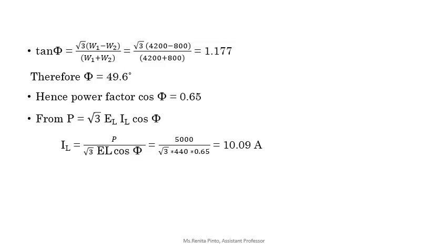Next is the power factor. How can you find out the power factor? You already know there is an equation: tan phi equals root 3 times W1 minus W2 divided by W1 plus W2.